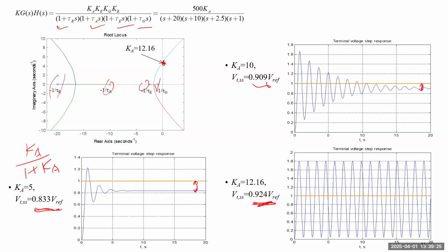Those 4 poles together determine each individual root locus. So we pay attention to the root locus that can intersect with the imaginary axis, for example, this one or that one. We don't worry about anything else. The others may change the time performance, but they don't change the stability of this system. So we just identify those 2.